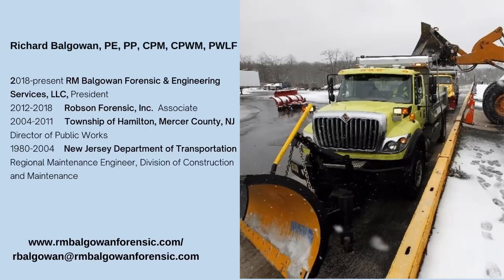A lot of agencies around the country are using these. It's called MDSS, Maintenance Decision Support System, to kind of cookbook things. I know snow and ice control is certainly not something that is cookbook, but it provides guidance and lets you know here's what's going on and here's something you should consider doing, right down to how much salt should be applied. So there's a lot of technology and a lot of systems out there that can be used to manage and monitor the amount of salt we're putting down on our roadways, and know that we're managing things to the best of our ability and not over applying salt.